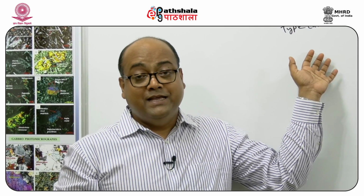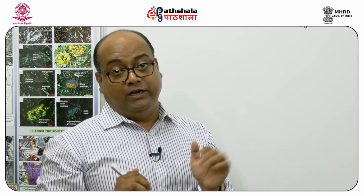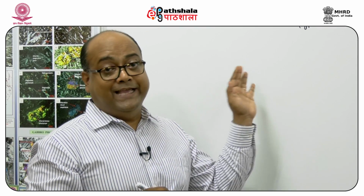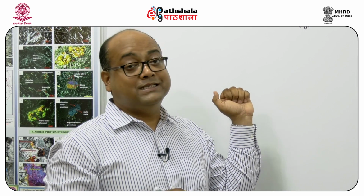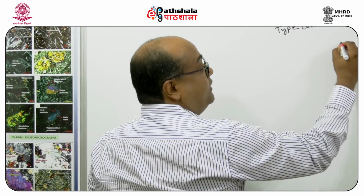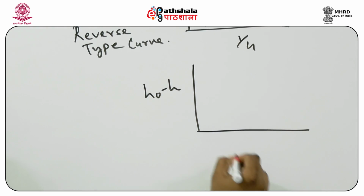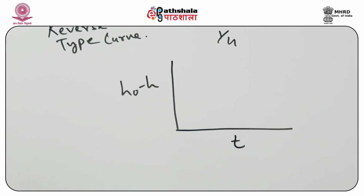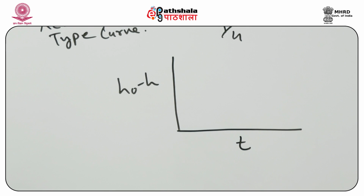Now, how is this curve used in the graphical solution? What we measure in the field is drawdown only, with time. So in a very similar manner, we plot H0 minus H against time on the x-axis, and again these two variables are plotted in logarithmic scale.